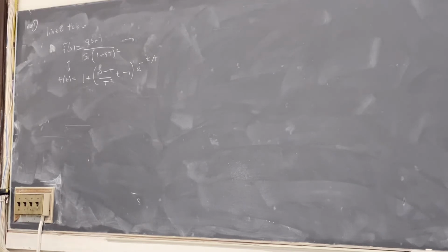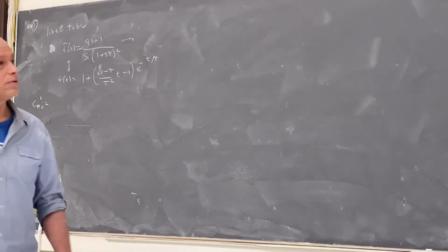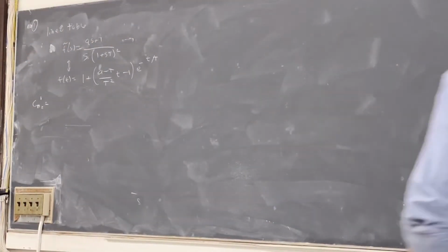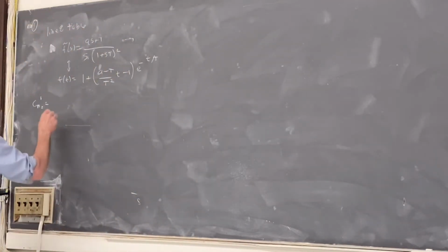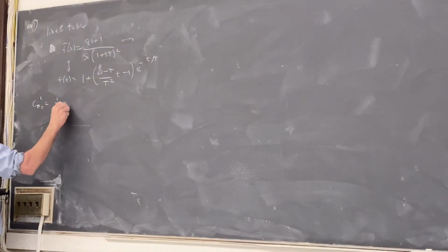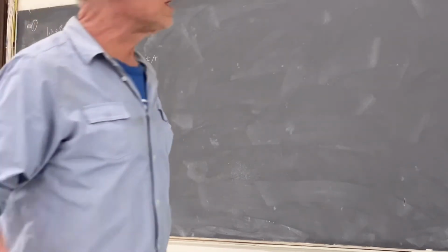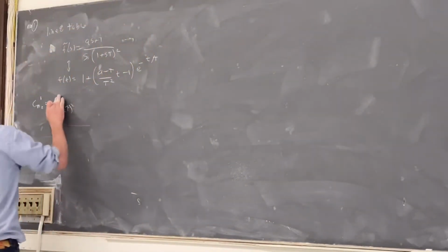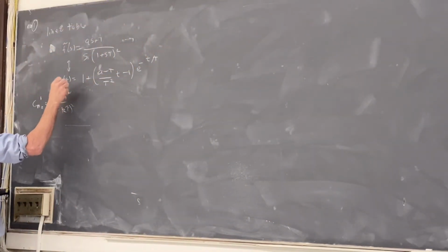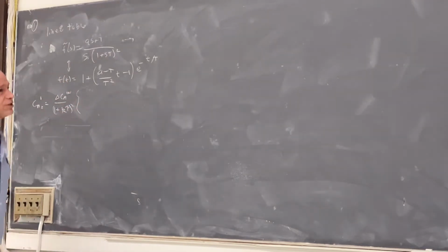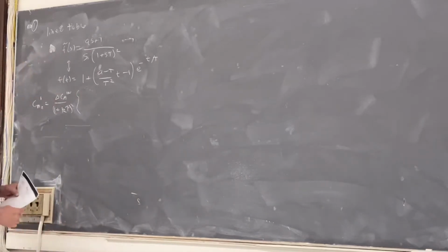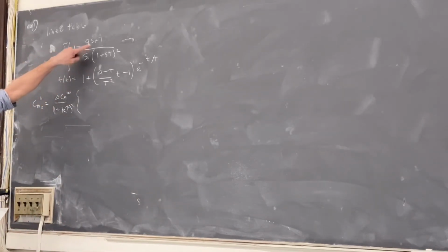So let's look at what we get here. This tells me that CA2 prime is equal to 1 over 1 plus kτ squared, because this is case A, where τ1 and τ2 are the same, times delta CA in, times, I think that's all the constants I have, right? Yeah. And now I just plug this in. Notice a is equal to 0.